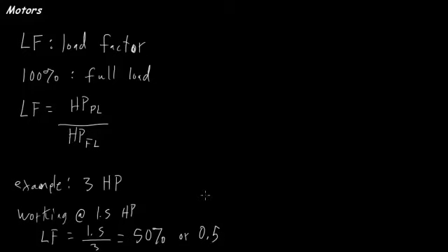So load factor comes into play when we look at HVAC systems a lot, because most of the time an HVAC motor is not operating at full load. It's operating at some point lower than full load. And if it's operating too low, that's an energy conservation measure, because if we can replace that motor with a lower horsepower motor, it'll be higher efficiency, because remember, the higher the load factor, the higher the efficiency of the motor. The harder it is working, close to its full load, the more efficient it is.